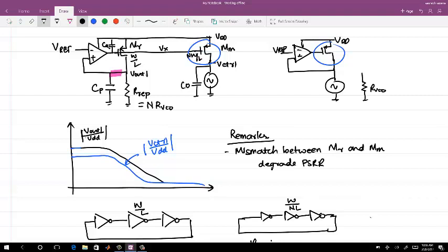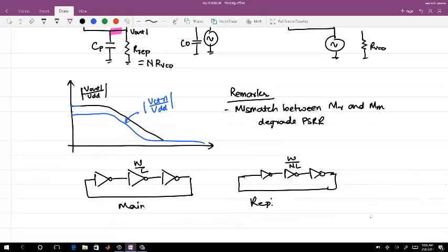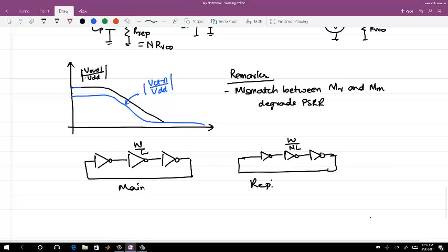So the replica regulator regulates Vx, and from Vx only it is regulating your V control. Yeah, that another pole will come. So that would be a good one to work out the whole expression, what it is, V out by V reference.